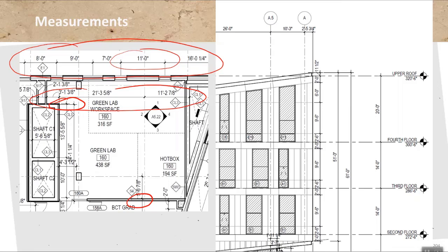Exteriors and windows, as you can see up here, can be dimensioned on their center line or on their rough opening dimensions. Traditionally, masonry window locations are dimensioned on their rough opening, because you need to figure out full brick lengths or block lengths, and then light frame, and in this case our exterior wall is steel studs. It makes more sense to lay these windows out on the center line, but again, this is very much project dependent, and it depends on what you need.